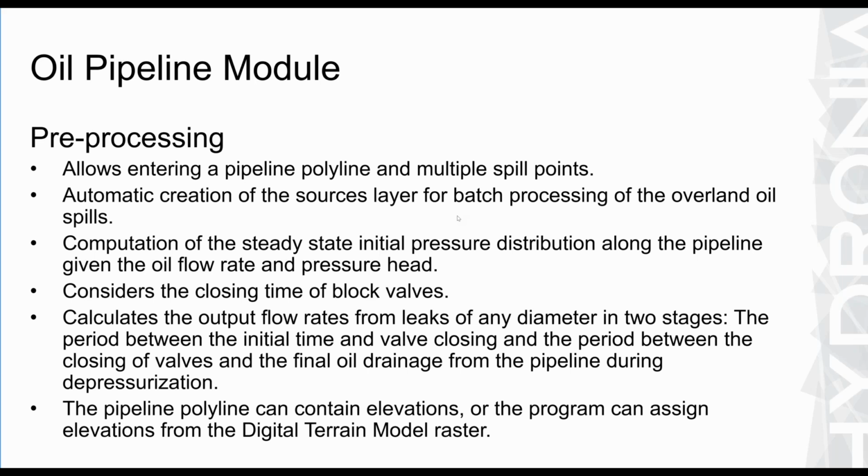It can consider the closing time of the block valves that can be in the pipeline to limit the outflow once the leak is detected. They're usually block valves that are closed very quickly in order to close the areas that are subject to these leaks and minimize the amount of oil that is getting out of the pipeline. The outflow rates are calculated for any user-defined diameter, in two stages.